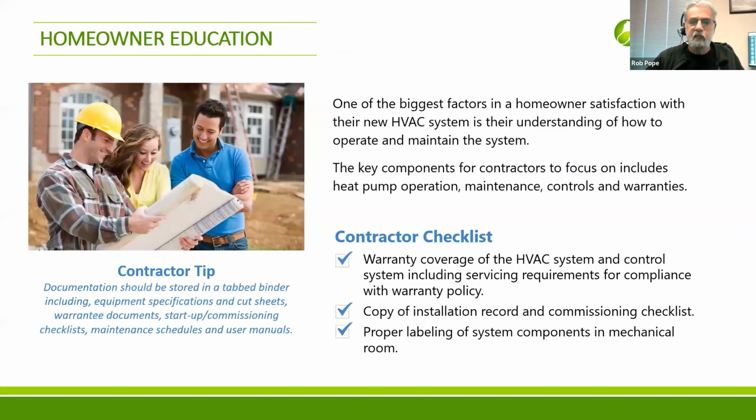And I think finally here, this is pretty important. I can't tell you how many times I've gone to a project or a job that had issues, and all it was, was that the homeowner had no idea that if you programmed it this way, it was going to take longer to get the heat up in the mornings, or the programming schedule was off, or they didn't know they needed to change a filter. It was filthy and blocking airflow. They didn't know that they've got the outdoor unit and pine trees all over the place, and a couple times a year you've got to clean those pine needles off it. There's a whole bunch of stuff.